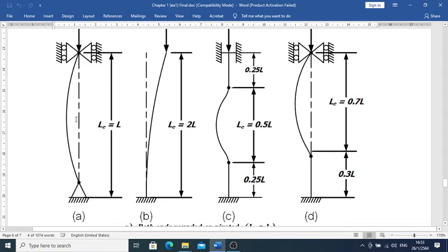The first end we just fix, and then we have a joint there, and another joint there. At the other end we just apply the force on it. We allow it to move in the up and down direction, but not sideways, so L sub E equals L, respectively.